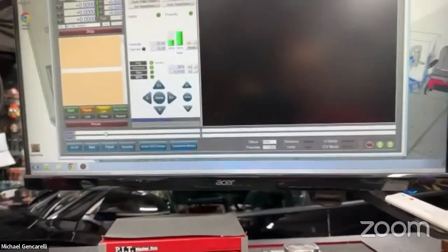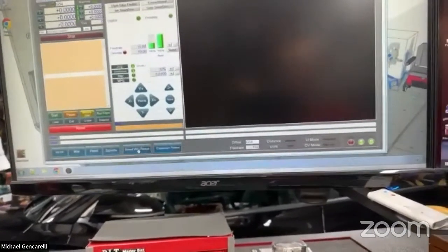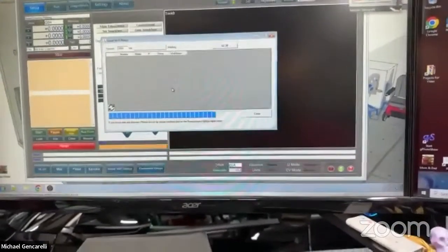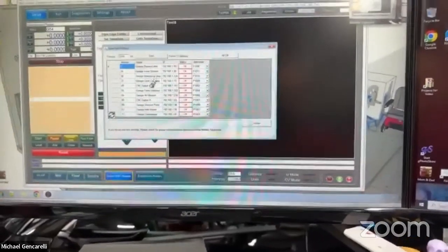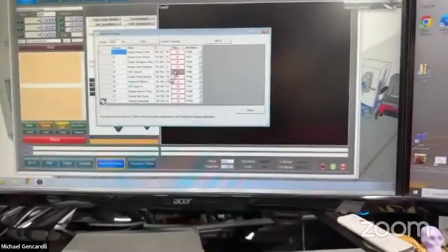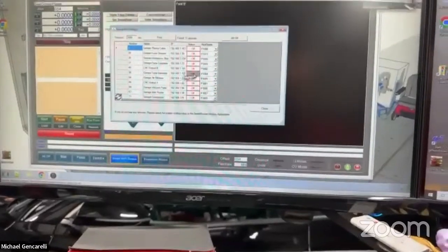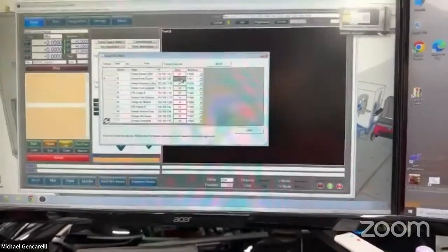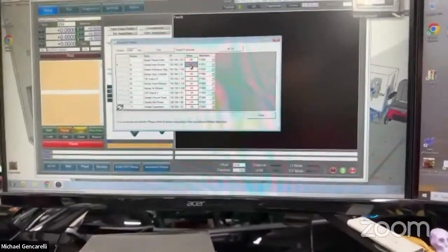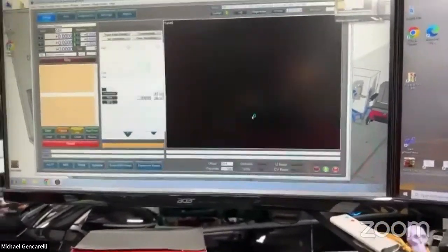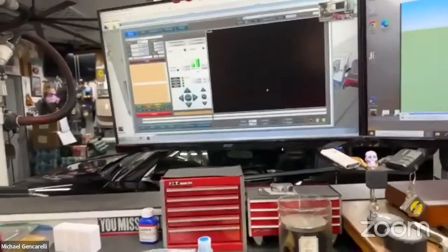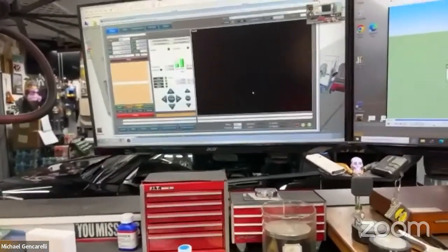Yeah. And so basically from Mach 3, through G code or through the UI, I can control a specific set of devices. I can turn on my compressor, my vacuum table, my plasma, my whatever here. Like a fume extractor, turn that on, turn on the fume diverter. I can turn on my compressor. Again, all of these things I can turn them on or turn them off. I'll just do all off. But I can do that also from G code. So my Mach 3 machine turns on the equipment only when it's needed, and when it's done with it, it turns it off.